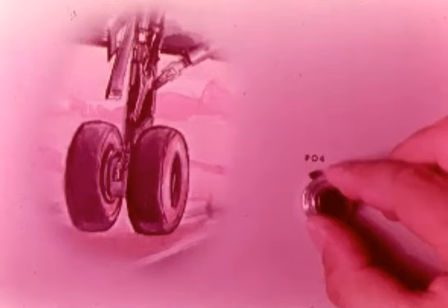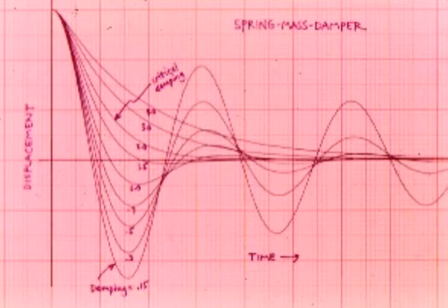Now, by simply turning a potentiometer, you can effectively change the tension of a powerful spring. The effect of changing each of the problem parameters, mass, damping, and spring constant, can be studied by drawing a family of curves. Questions such as, what happens if both spring tension and damping are increased as the mass is decreased, can readily be answered. The response of the system to various disturbances, transient, cyclic, and random, can be analyzed and predicted. The best values for a given set of design criteria can be chosen.